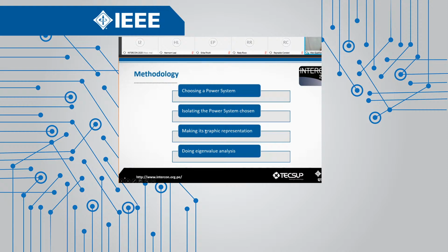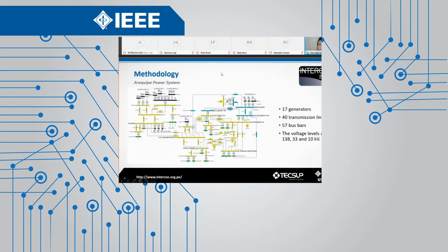The next step is to make the graphic representation. Here you can see the graphic representation of Arequipa's power system. Some information about it: it has 70 generators, 40 transmission lines, 57 bus bars, and there are colors that represent the voltage levels. In this case, light blue represents 138, yellow represents 33, and green 10 kilovolts.